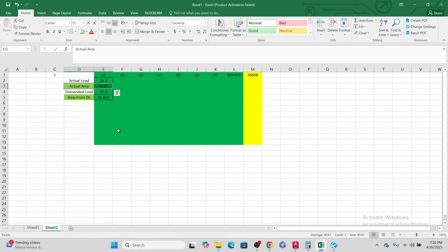In case you have a function with too many people, a situation can come where everything is on. And another case, maybe you will bring in an additional device, something special. So you will not have any problem. So for the DB breaker, with the 40, I will go with the market available breaker, maybe 60. We will always go bigger, not the actual ampere breaker.